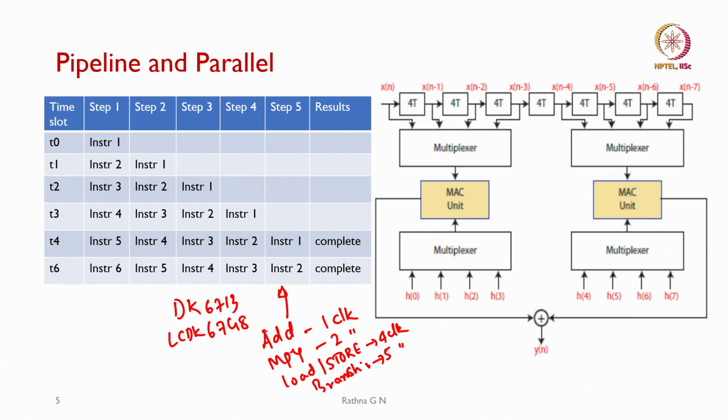Some of the instructions, I will come to them in a while, we may not know how many clock cycles they take, then we call them complex instruction cycle. Basically you would have heard of RISC and CISC. So, a DSP processor most of the time, 80%, is going to use a RISC architecture, and 20% for our circular buffering, and FFT operation, where bit reversal has to happen, they use CISC architecture for that, and this is what we call pipelining.